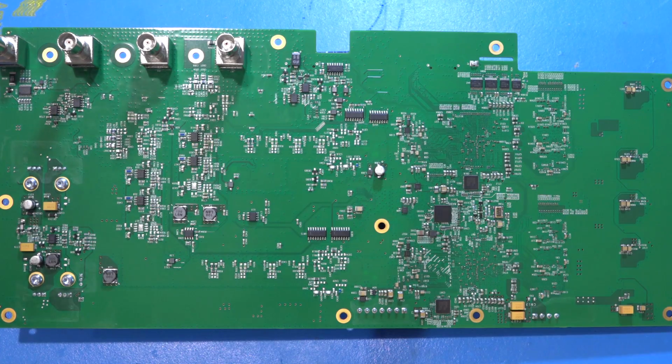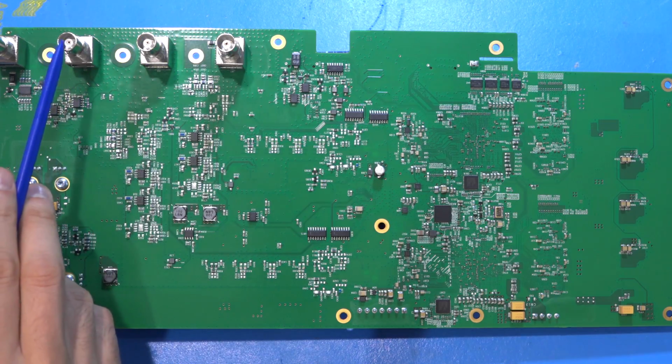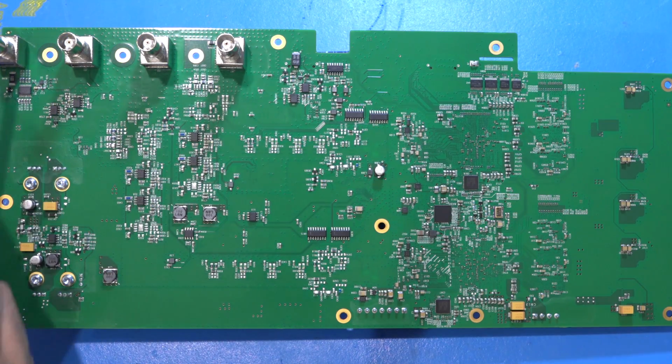And here's the back of the board, and we can finally see the rest of the components that I was referring to. So here are our analog outputs, channel 1 and channel 2, and trigger input and trigger output. Next to the trigger output, we have a driver IC, which is to be expected. You want to have something that boosts and ensures proper impedance of the output trigger, so you can get nice edges on that. And then on here, you can see two ADCs. These are the ADCs I was referring to.